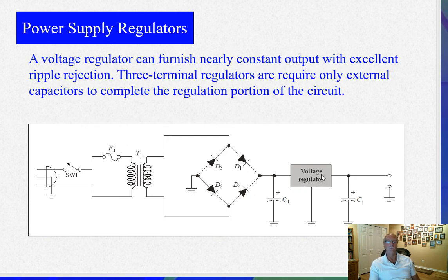And the whole job of a voltage regulator is to isolate the load out here from fluctuations on the input voltage. The other job of the voltage regulator is to maintain a steady voltage on the output if the load changes. Okay, so there are 2 different things a voltage regulator does. One is maintain the output voltage when the input voltage changes, and also it maintains the output voltage when the load changes. So for example, if your voltage regulator is a 5-volt voltage regulator, right?